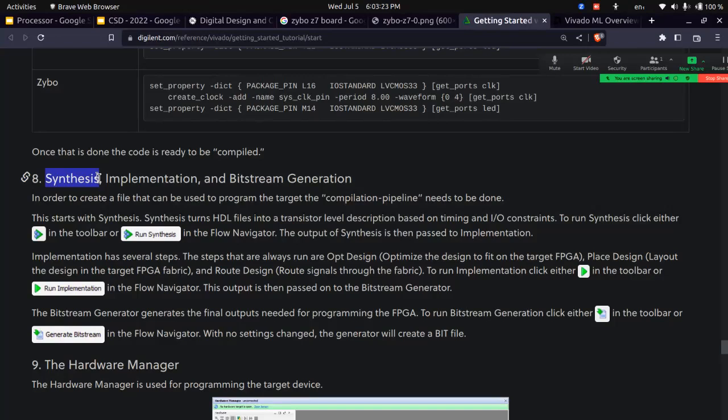We did the complete documentation: what is the reason that this particular line of code is not getting synthesized properly? Because there is a style of coding also. In a digital system lab, there is no style; you write just like a C program and it still works. You only use delays or timeouts, and you use many Verilog constructs that make writing code easier. But you cannot use those things here. It's not like C programming. It's a different thing, so you have to write synthesizable code.